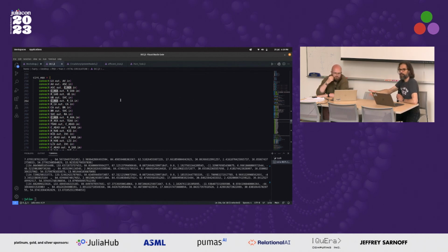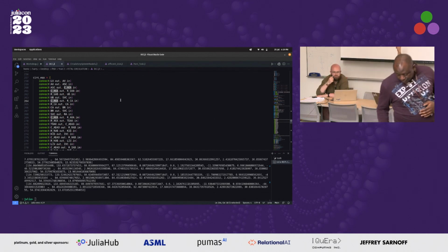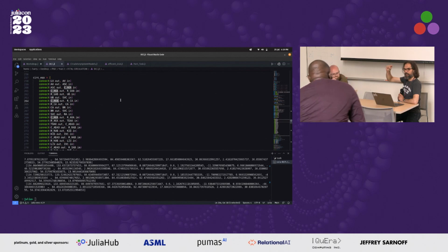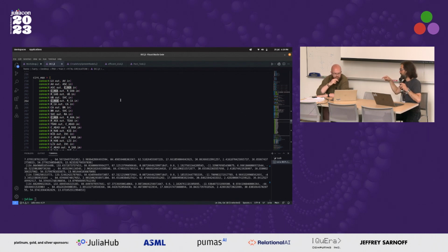It's a logical function, so you can implement it in code, and then just output that connect statement. Because the way acausal modeling works in principle is you define a function, and that function gives you an ODE at the end. But within the function, which is basically the compound model, the connect statement gives you an equation, not an ODE, but an algebraic equation. And then you combine that with the ODEs in the individual elements. That's what the